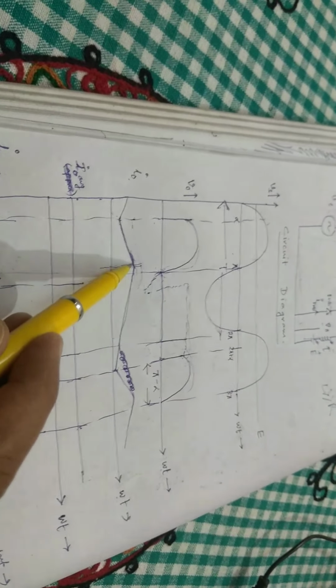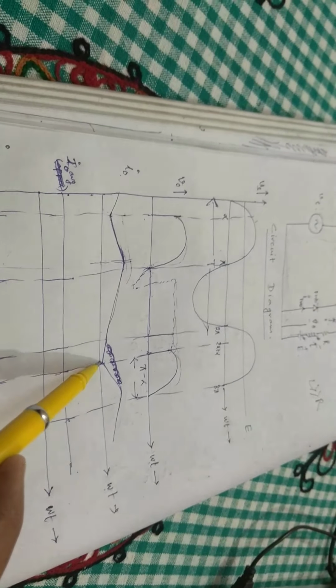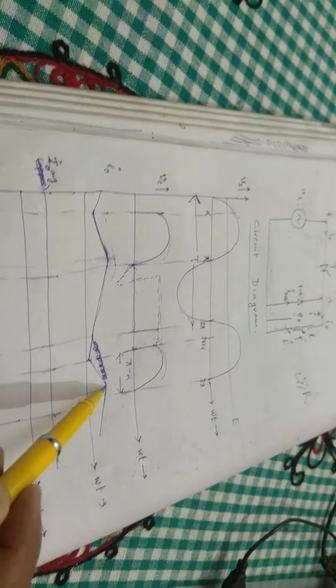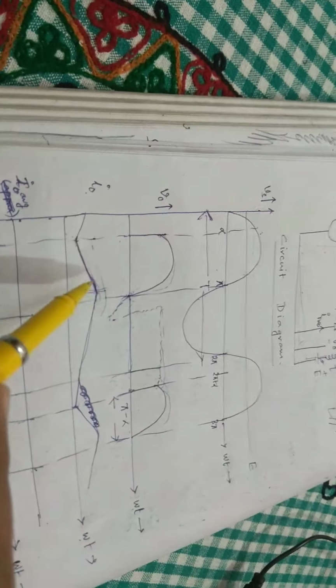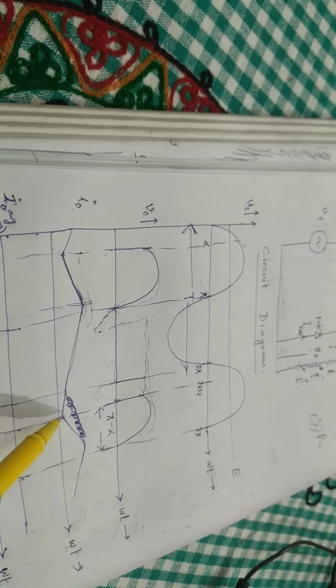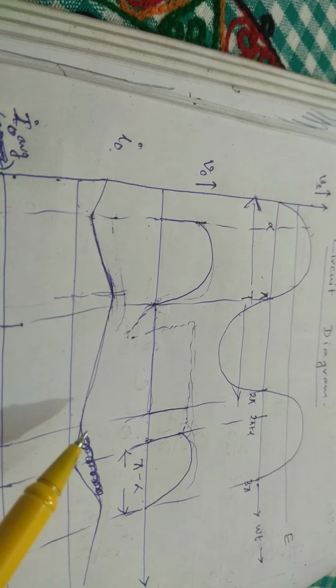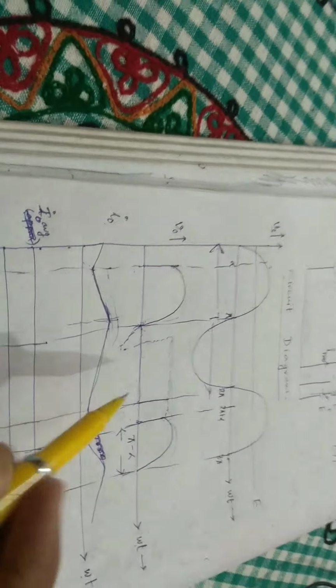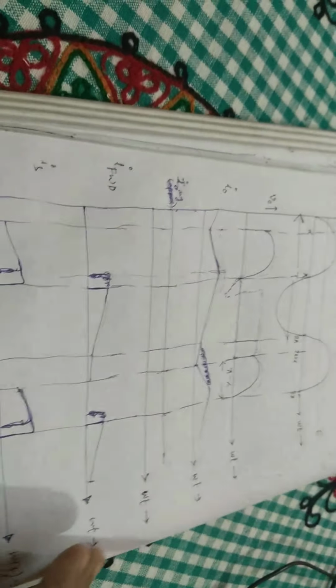So the current charges up and rises, then decays till 2 pi plus alpha, and then starts rising again as and when this thyristor T is triggered. But such a long decaying period is a bit abnormal. We have to show this operation in the continuous conduction mode, and therefore I have shown that this current does not become discontinuous. So this is my I0 and this is my I average. I have considered it to be a constant DC current.